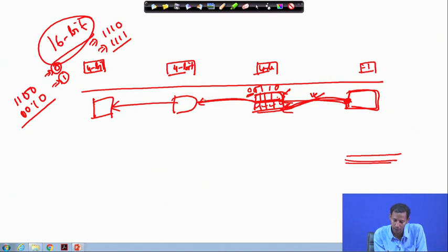As this is also not producing any carry over here, again this value will have 2 sets of sum bits. So 0 means I will choose this particular case and not that case. Again, this also has 4 sum bits and its carry output bits, so based on the carry output over here, it will select the corresponding values.